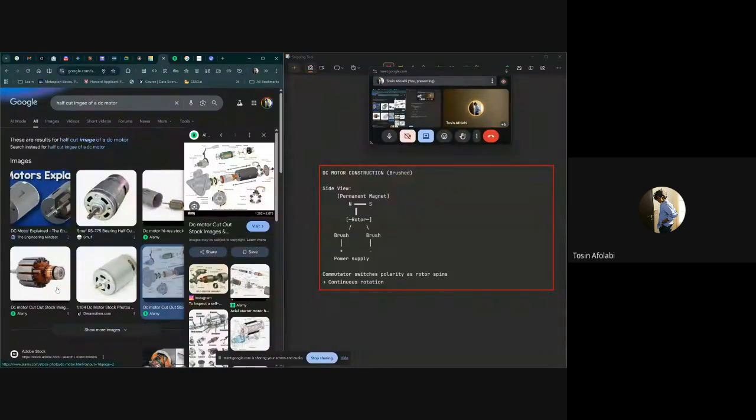I also explained it in the last class, with the way the LCD works, the SDA and SCL lines work and everything like that. So more information is in the previous classes' recordings, to be exact. But in relation to speed control, a 100% duty cycle is always on. That's the full volt. So the Arduino supplies full power to the DC motor, meaning we get full speed ahead.